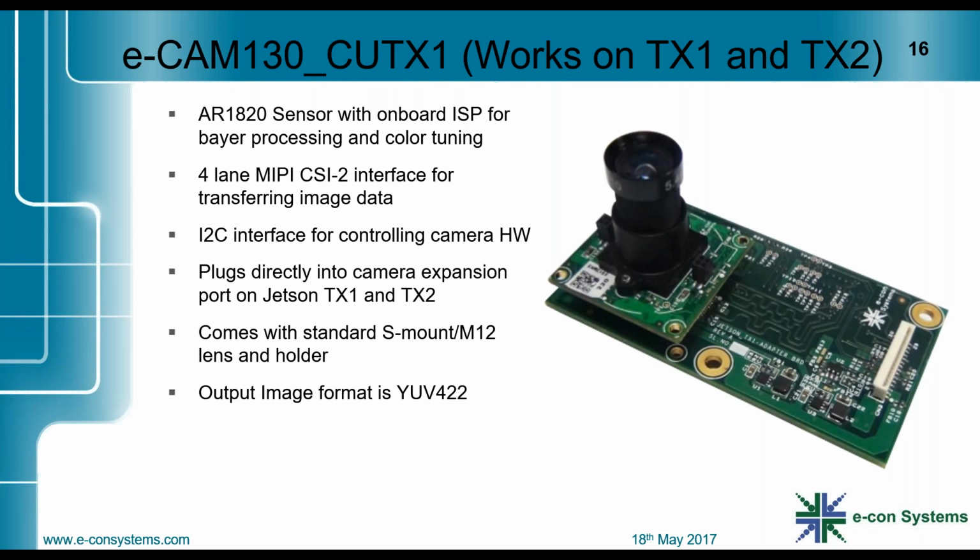It uses the 4-lane MIPI interface on the TX1 or TX2 for data transfer, while controlling the camera can be done using the hardware I2C.